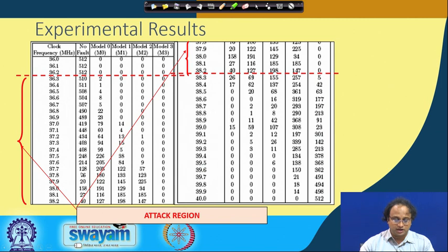The interesting thing is that this characterization can be done per device, and it seems that even if you shut down and restart the machine, you again get a similar kind of characteristic. So you can study a platform, and based upon that find out your ideal clock frequency selection, so that you get faults according to model M0 with more probability. But even if the fault propagates to more than 1 byte, as long as it is restricted to one single diagonal, you can still apply these techniques.